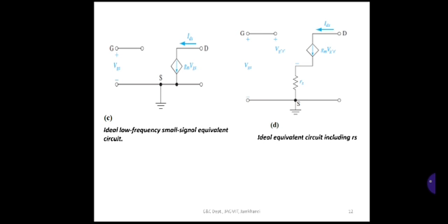So here the diffusion resistances are infinite, the series resistances are 0, and the low frequency capacitances become open circuits.